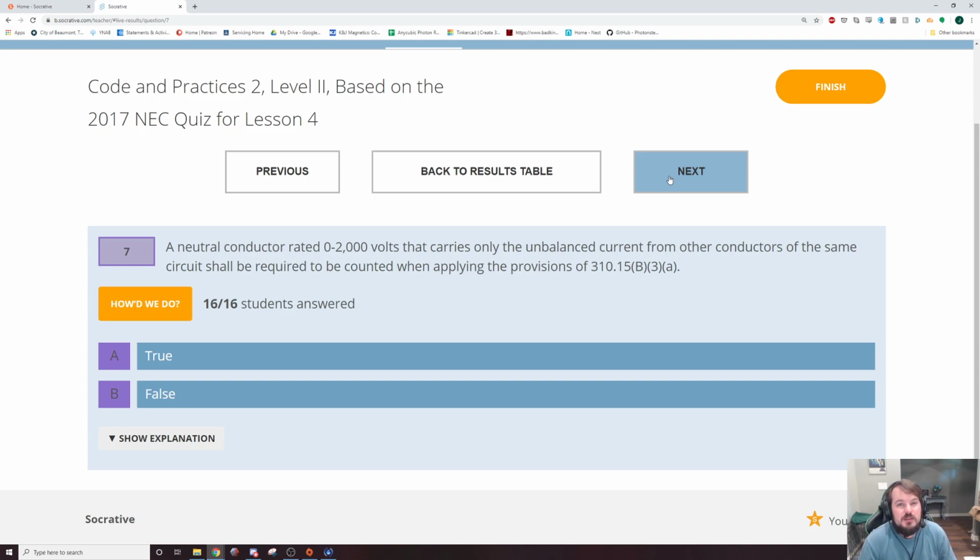I guess that would be the most reasonable example is where you have like two big motors installed and they're like 50 feet away from each other and you want to eliminate one of the motors and put a bigger motor in the other spot. So you're like, I'll just parallel it, and you just run a conduit to extend that wire back where it had gone. It would be smarter.